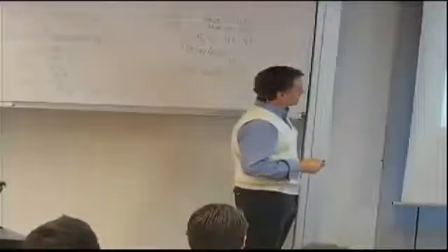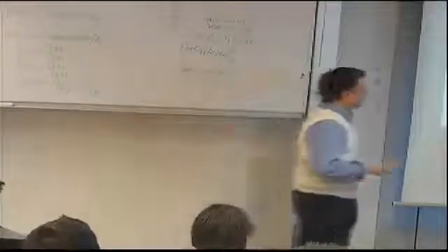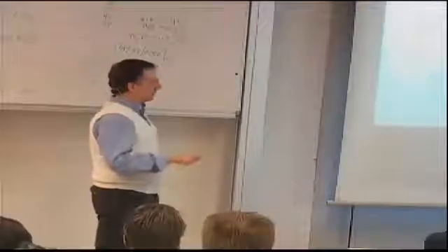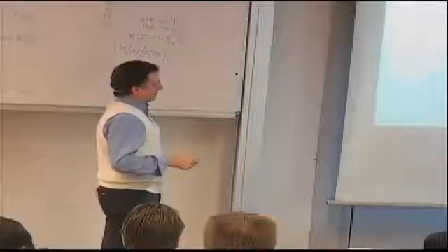When I eliminate u and v from these three equations, I arrive at the classical compatibility equation that only involves the strains. But I know the strains calculated here, so I can substitute into this equation for those strains to get this, which now involves the stresses. And now I have the equilibrium equations that I just showed you at the bottom here, two equations. So I can eliminate two of the stresses in this last equation to arrive at a single equation that will involve only one stress. In this case, it's the sigma x stress. Notice this is my xy coordinate system, so x is pointing down in the plate that we have there. Fourth order partial differential equation with beta and gamma as defined here.